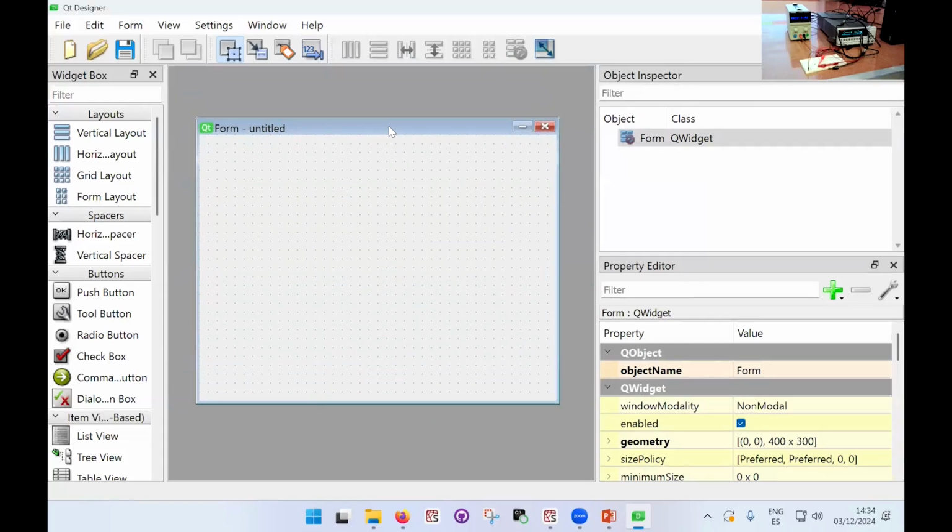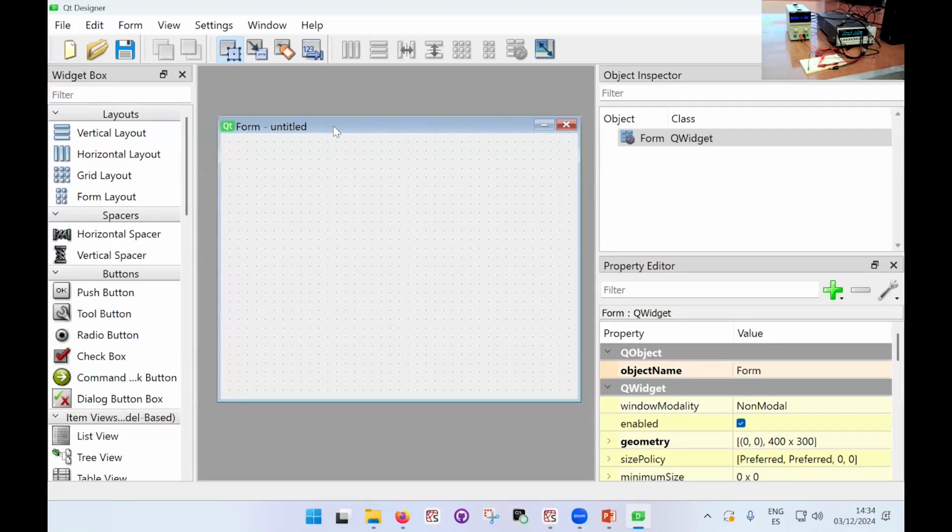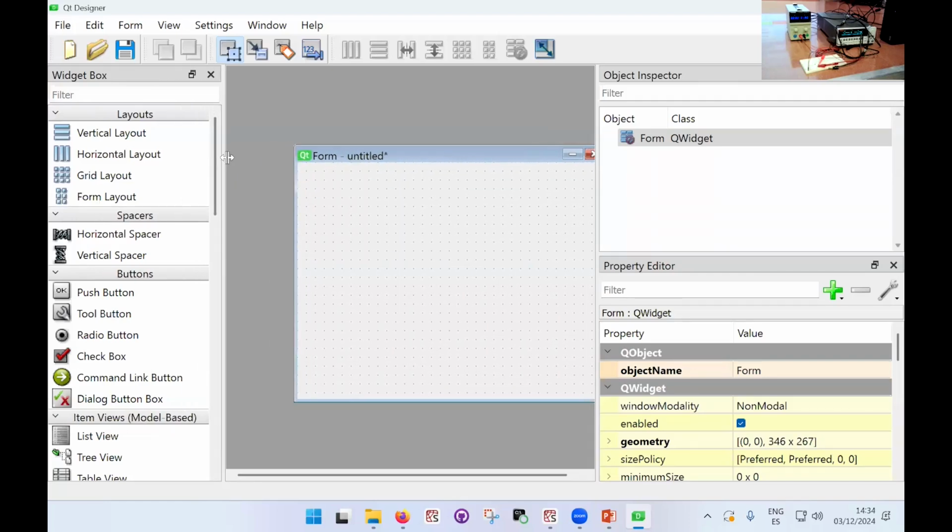So what is it that I want from this experiment? So the first thing that we're going to implement is the linear sweep. Okay, so we're going to put a sweep from a starting voltage and end voltage. We're going to implement a step and a button to execute the sweep and actually get it done. So I'm going to put this that way. It might not actually need to be that big.